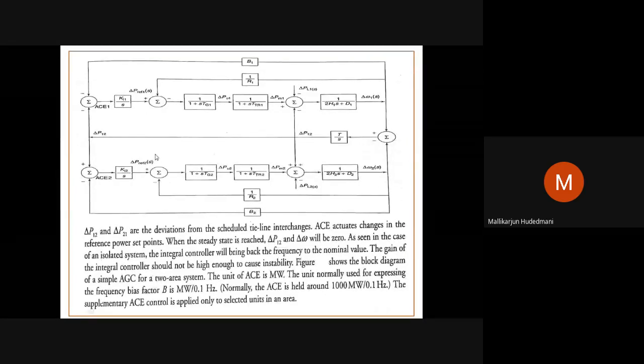Now, due to the interconnected mode of operation, whenever there is a change in load in area 2 which causes a change in frequency, let area 2's generation only work to overcome that frequency deviation. That was the objective with which the supplementary loop was focused around the existing primary loop.